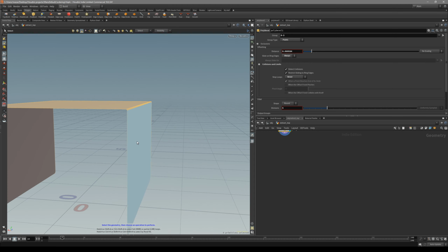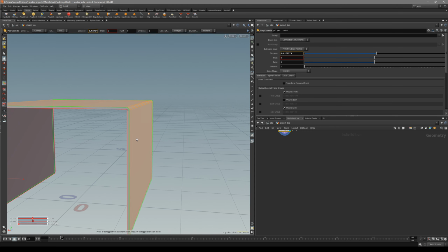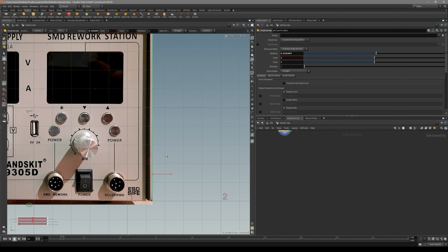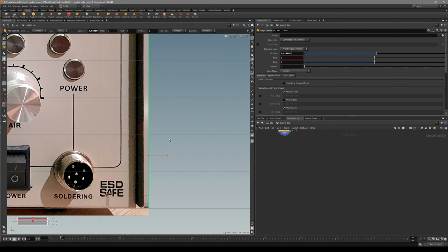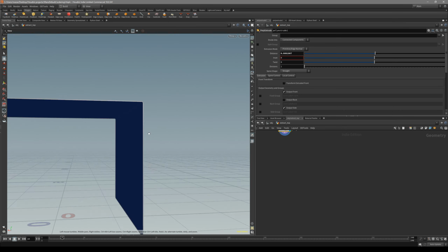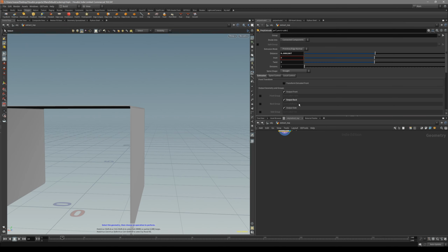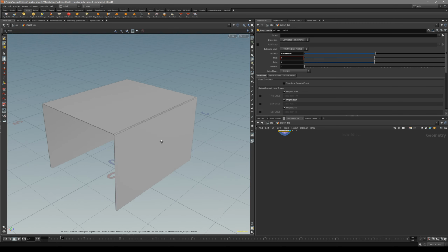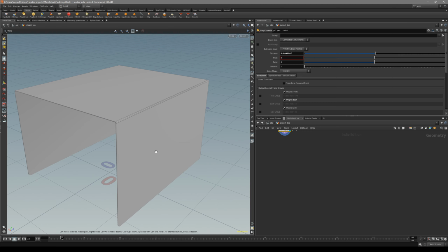So let's select these and let's extrude. Let's extrude outwards, so find the handle. Let's go for this. You can press the middle mouse button and we can change the value later. For me it's not super big, something like this, looks fine. So it is not very thick metal at all. So also extrude back like this so that we have a closed volume in it.